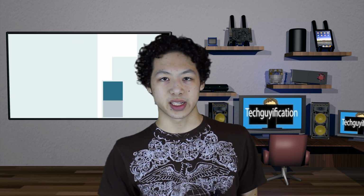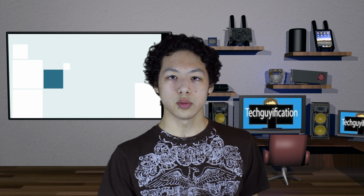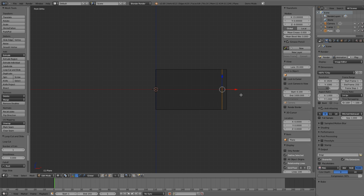So with this edge loop selected, place it exactly by going down in the properties panel to under where it says transform, and then the top of that is median, and the first one is the X value, so set that to 15. And also make sure that the median is set to global, not local. Press the A key to deselect the vertices, and now we're going to go into vertex selection mode. So you hit that at the bottom of the 3D viewer, there's a little button where it says vertex select.